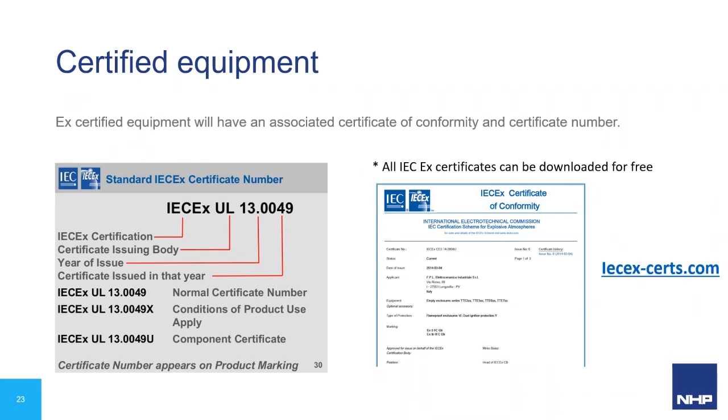Now, all the necessary information is in the IECEx Certificate of Conformity, and luckily these can be downloaded online for free from the IECEx website that you can see written there. Generally all you need is the certificate number and you can start browsing through the certificates.